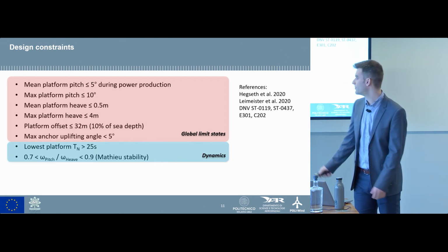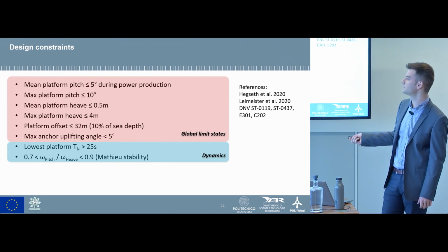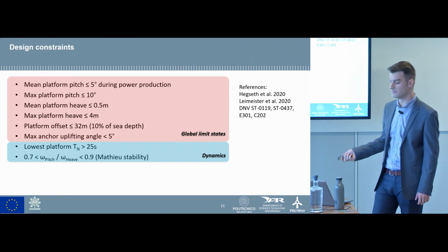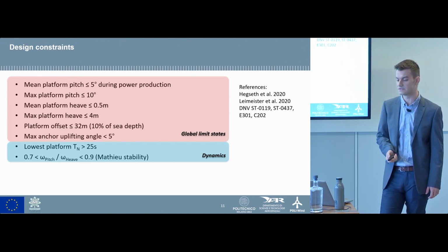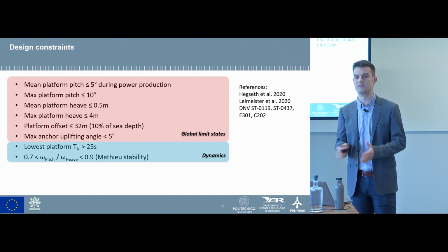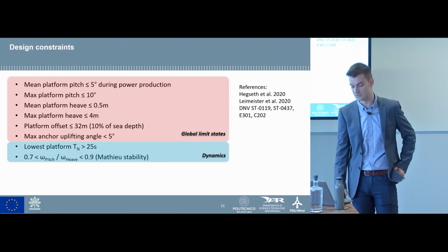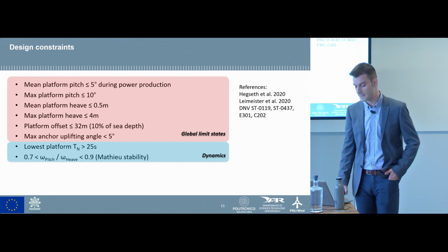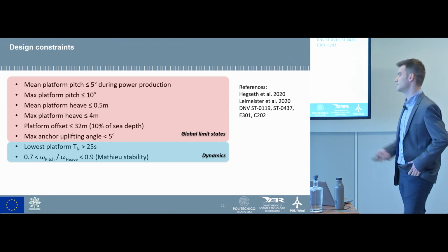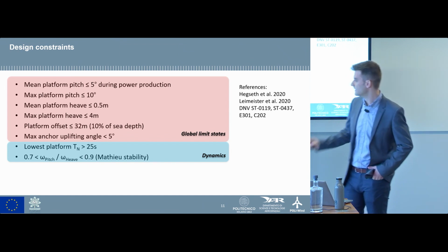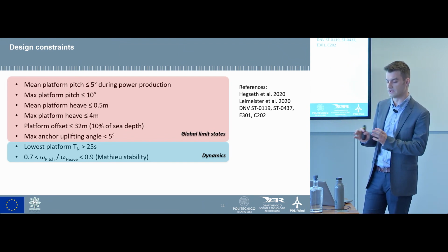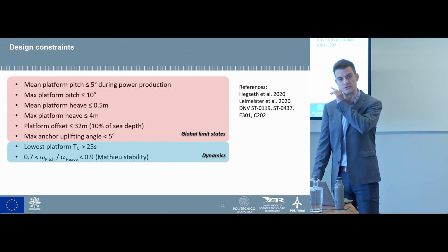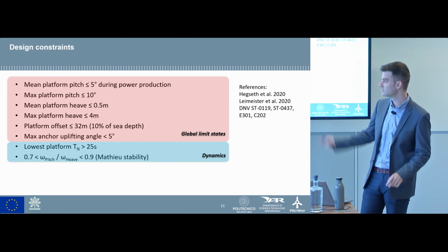And we also incorporated the dynamics constraints. So the lowest platform natural period needs to be above 25 seconds to prevent resonance with the wave excitation. And in order to ensure Mathieu stability, we have opted to put the ratio between the natural frequency of pitch to heave in a certain window that you can see here.